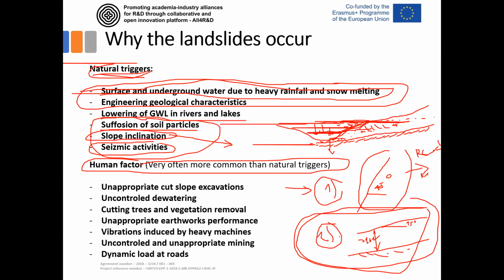You can excavate that part and bring a relatively small retaining wall above, and it will stop it from sliding. But when you have deep soil-like material on a relatively flat area with a small slope angle, then it can be a real problem. Most landslide related problems really occurred in areas sloped about 10 to 15 degrees to the horizontal.